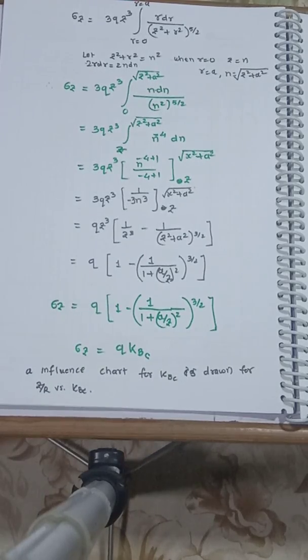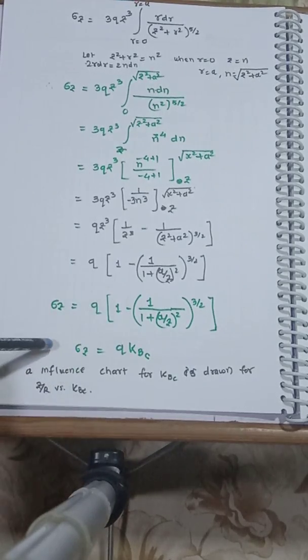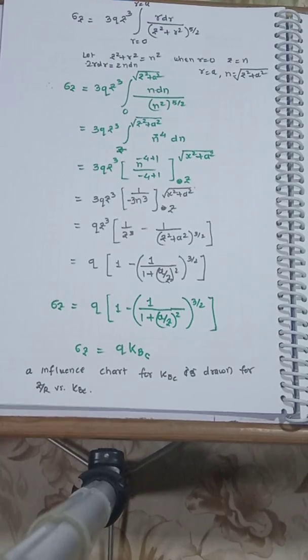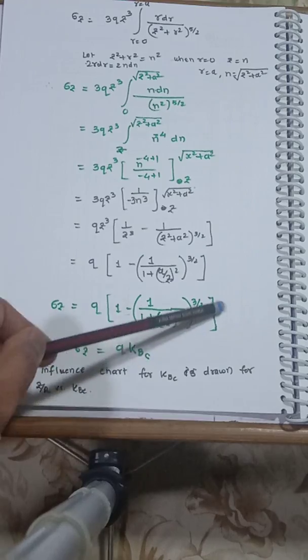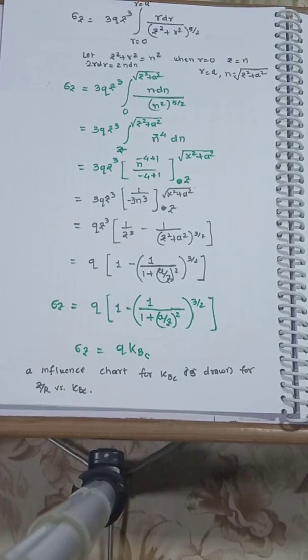Earlier also we found that there was an influence factor for a line load, and from the influence factor we can draw a pressure distribution just like for a point load. You can draw, at a constant depth, a uniform distribution on a horizontal plane. Similarly, at a constant radial distance r, you can draw a vertical distribution. And also you can draw an isobar by using this influence factor, as we have discussed earlier for the horizontal distribution, vertical distribution, and isobar. The procedure is the same.